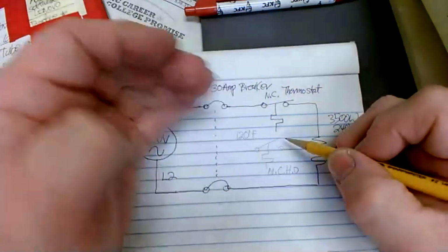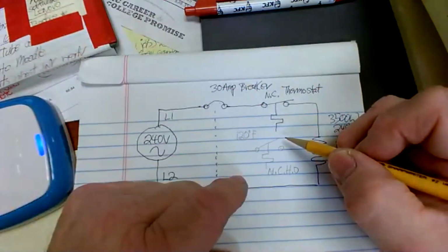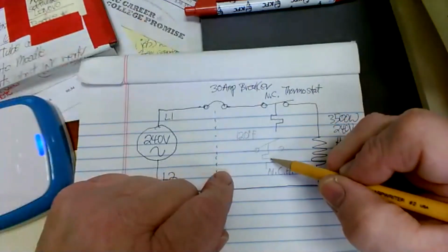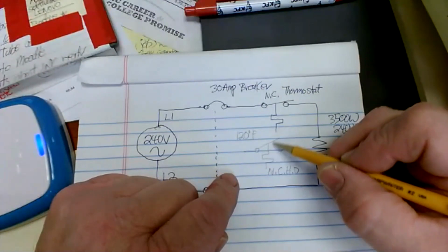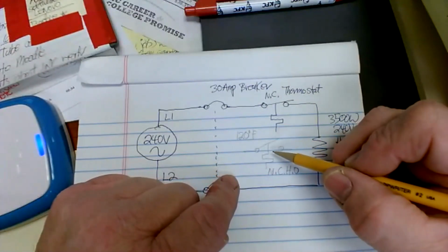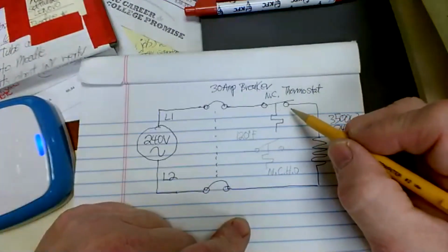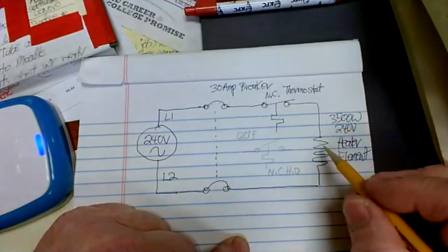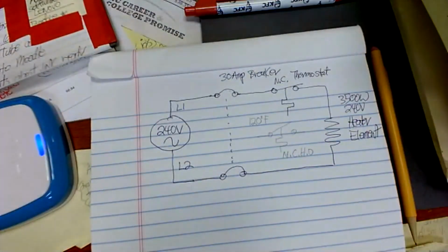But as you use water and more cold water goes into the water heater, then this is going to cool down, right? So when it cools down, what happens to this? It closes. It's gonna lower the drawbridge. It's gonna close, and then power's gonna flow again through the heater element, and it's gonna try to build up heat in there again, to heat the water. Right.